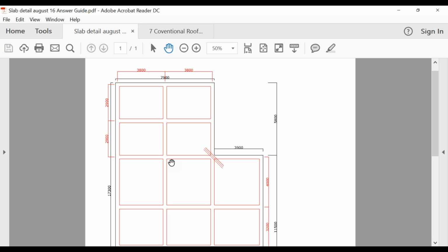But when you ran the internal beams across, they were pretty much lining up with another corner on the other side, or if it was pretty close. That's where I realized I could have probably done an internal beam on an angle and caught it. Yep. But it was also close enough. I just thought, no, I'm just going to put it on every single internal corner anyways, because it was pretty much 4 meter centers, approximately, give or take, when you looked at it that way.